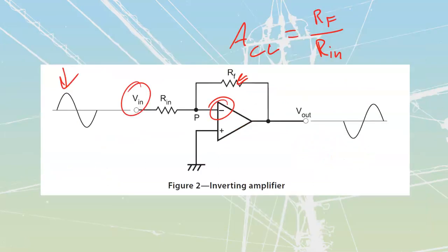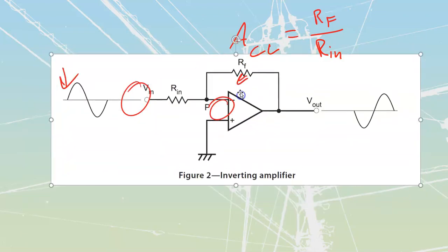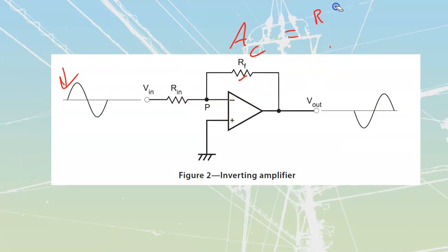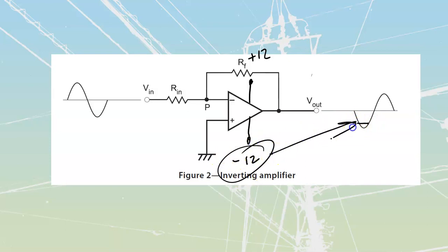Once again, the amount that it's going to go to is still going to be governed by whatever I've actually got. We talked about how what it dreams of being able to do is going to be different than what it absolutely can do. So if I needed to get 11 volts out on this thing, I would need to have at least a minus 12 volts and a positive 12 volts over here, because otherwise, if I was trying to do an 11 volts output, it would clip, or I would lose part of that waveform. My output waveform would get clipped off at whatever the maximum value of voltage would be for that.